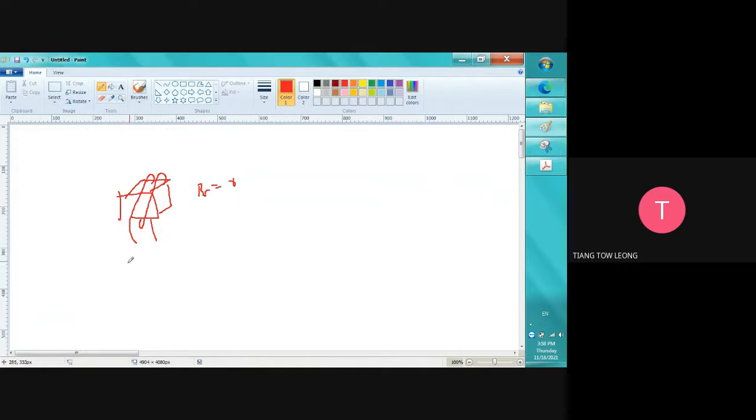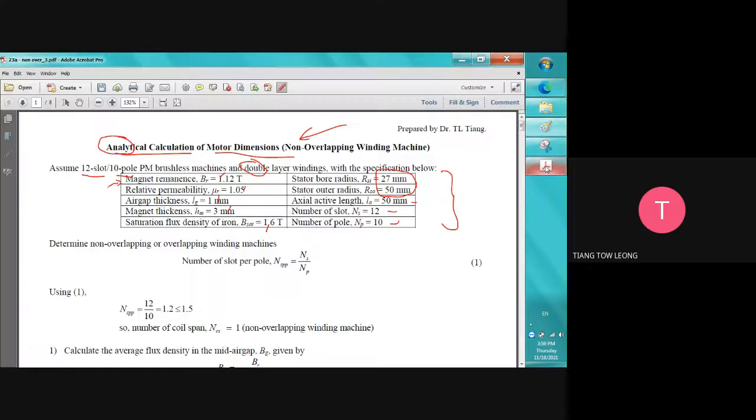After that, when we excite it, Br becomes 1.12 Tesla, even though we take off the excitation, I equals 0, it becomes a simple magnet. It has north and south pole, and when we put steel near to it, it will attract it, right? The capability of creating the flux is the 1.12 Tesla. This is the power of the magnet.